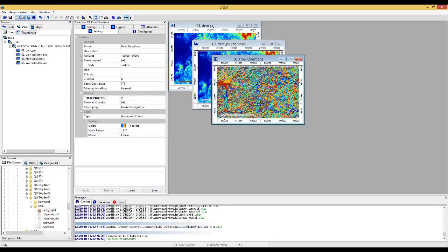The tool we just used also holds the flow direction function that computes the flow direction for a given grid. The value in any given cell of the flow direction grid indicates the direction of the steepest descent from that cell to one of its neighboring cells, using the 8 direction per point D8 method.